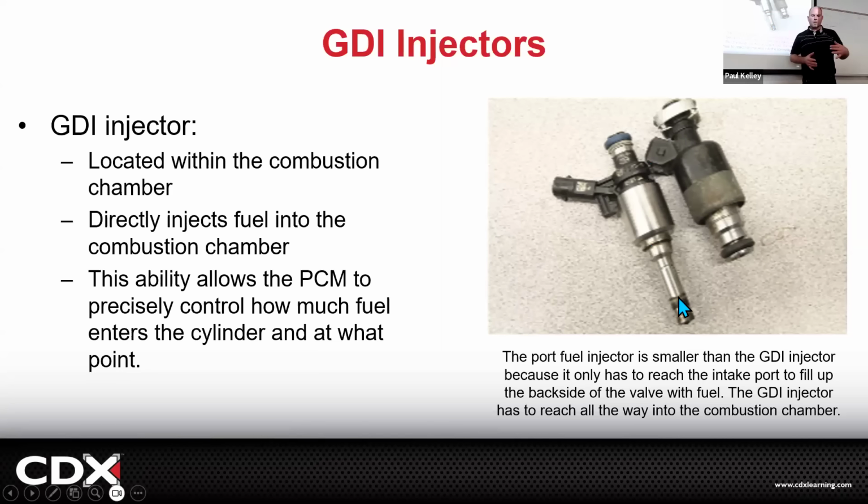So I'll give you a couple little inside points on this. Because this tip of this GDI injector is literally going into the cylinder, there's flame and fire and heat and compression, and it's exposed to a lot more. This O-ring, it's too weak. It's not even close to being able to handle that. Now that one's going to get burnt up. So we don't do an O-ring, we do this Teflon seal.